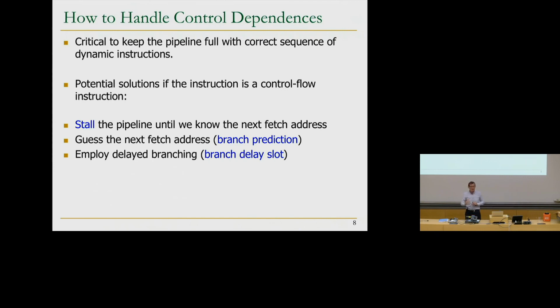Because what it's really doing is you're tying the pipeline length to the ISA, which is not good, because your pipeline length might be 2 stages today, which means that you may need 1 delay slot. Or if your pipeline length becomes 20, what do you do? Do you have 20 delay slots? Not good. So that's why we didn't cover it. But remember that this is one way of solving the problem. Do something else. You've seen fine-grained multi-threading. Basically, this eliminates the problem.